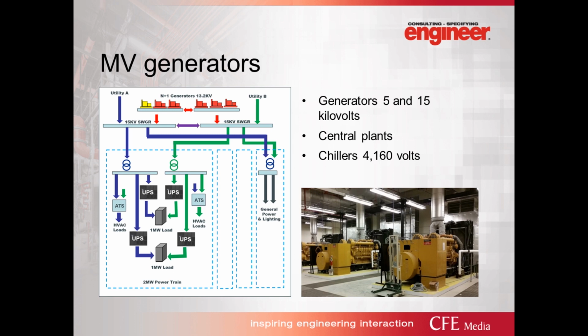You see medium voltage generators usually at a central plant where you parallel them. That's a diagram on the left. It shows multiple generators paralleled, and then you would feed that 15 kV, which then would distribute out to the different buildings or different areas on the campus. For low voltage, you typically wouldn't parallel more than a couple engines just because of the switchgear. Once you get into 5,000 and 6,000 amp switchgear, you're starting to get custom made. Where at medium voltage, even at 6 generators, you're still only around 400 amps, so that can be easily paralleled onto one piece of switchgear.